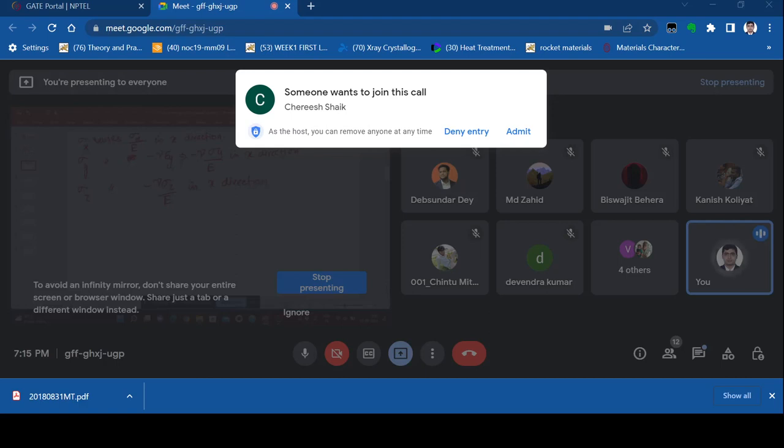So as we can see, when we are applying stress in 3 dimensions in x, y and z axis, then in x direction only we have 3 components of strain, this one, and this one. So now we will apply the principle of superposition. So our total strain in x direction will be, so we'll take this 1 by E outside, sigma x minus nu times sigma y plus sigma z.